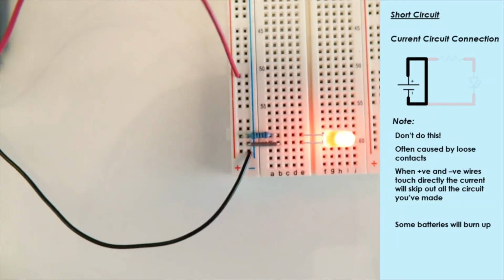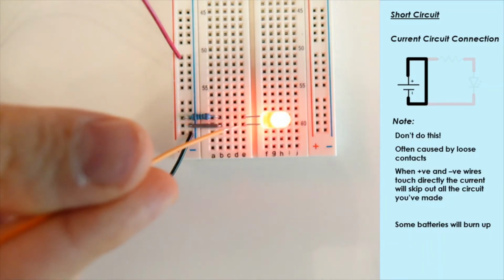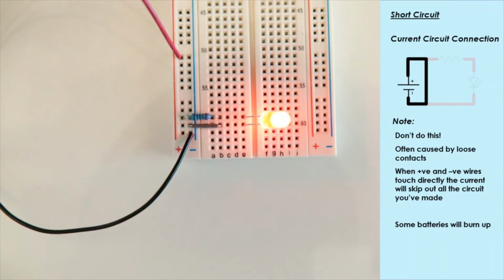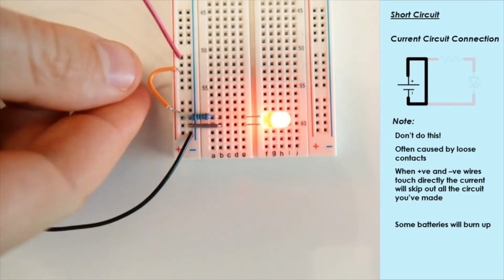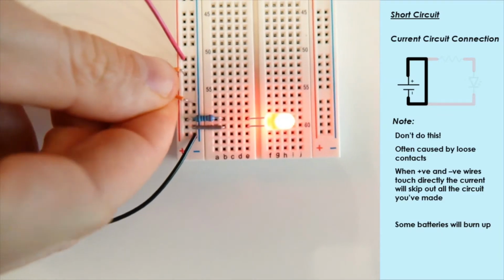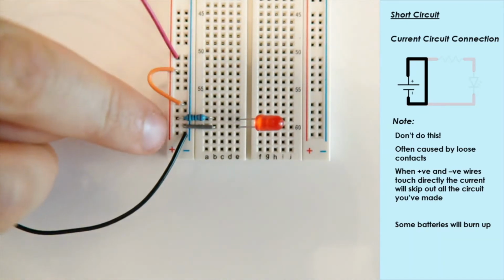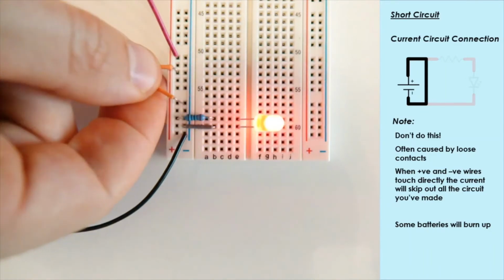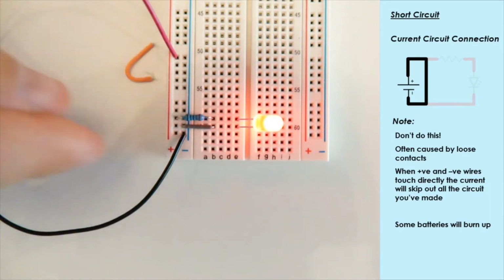Now, if we take a look at this simple circuit that we were looking at before, where we have our resistor connected to our LED, connected to our ground, and that's it. Now, if I take a wire between the positive terminal here and the negative, all I have done there is connected the positive of the battery to the negative of the battery using this one cable. As you can see, the LED has gone out. If I disconnect it, the circuit is restored, and this wire is incredibly hot, I can tell you that now.